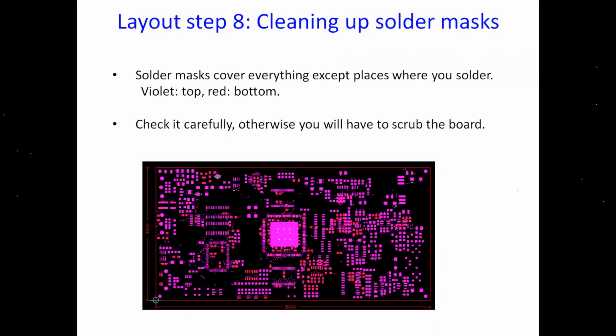And of course, finally, the solder mask layer also has to be considered. The solder mask is a completely non-conductive material, which is coated on the top and the bottom layer. So the mask should not be poured on the pads. That is, the pads are the access points where we mount the components, right? So if you coat the mask over the copper pads, you will get a short. You cannot solder the pins. So you will have to have a clear opening on the pad side. The rest of the portions can be masked.